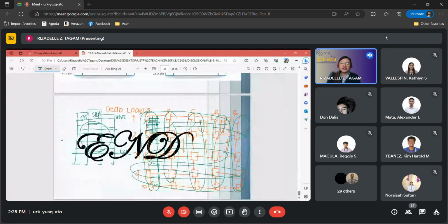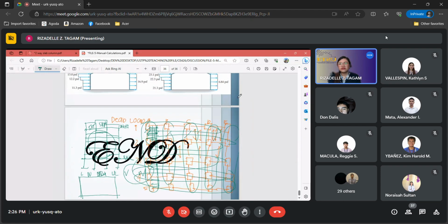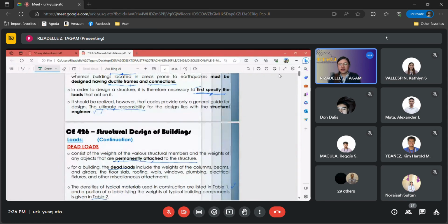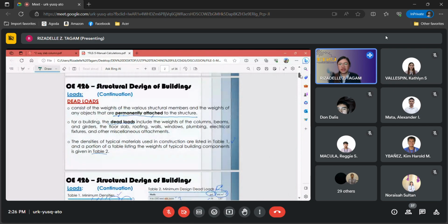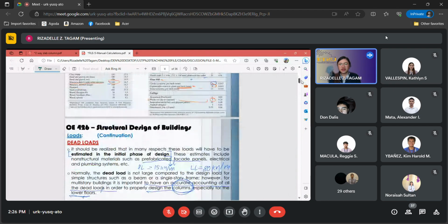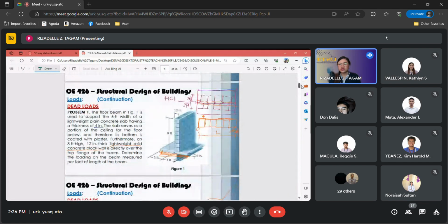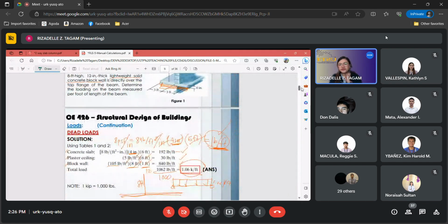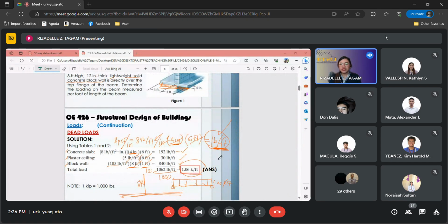And then, present a table form in Excel showing how you get the uniform load: the length, the width, the standard unit load, the uniform load, the shear, and the moment value. Put it in Excel. That is what you will do by the time you finish the beam layout. We have a deadline, so you can start this next week. That's all for today.